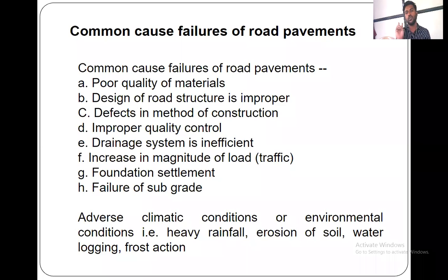So we have to do two things. One, we have to design for the maximum load that will be carried on that road. Second, if we have designed for the low load, we have to ensure that heavy duty vehicles are not allowed on that road. That care we have to take.